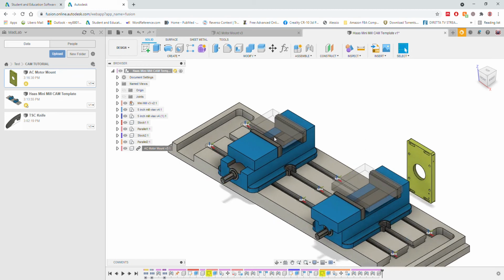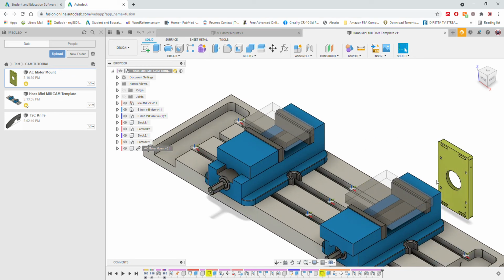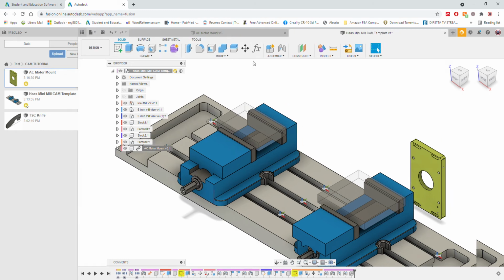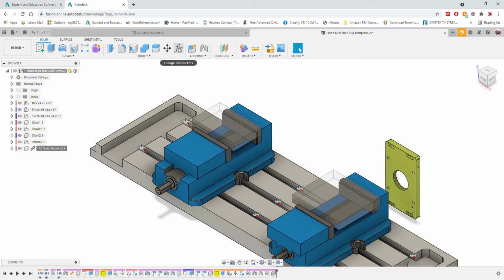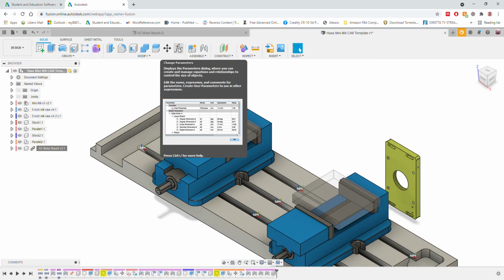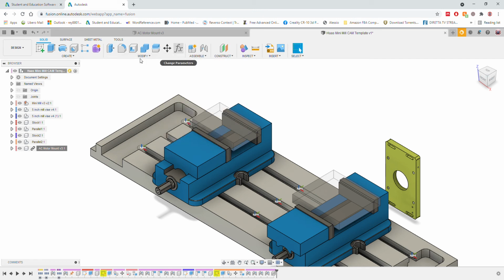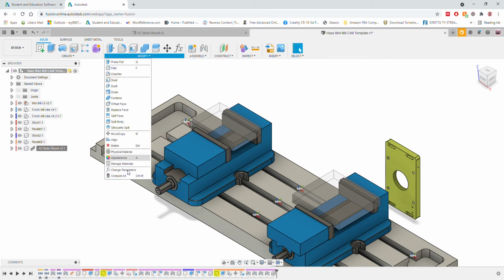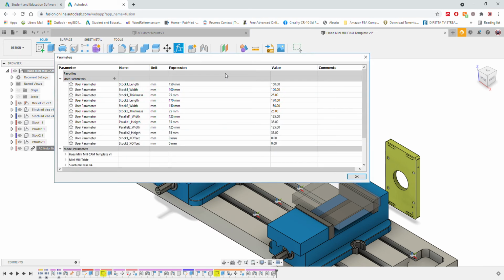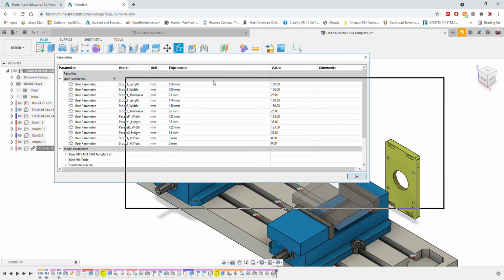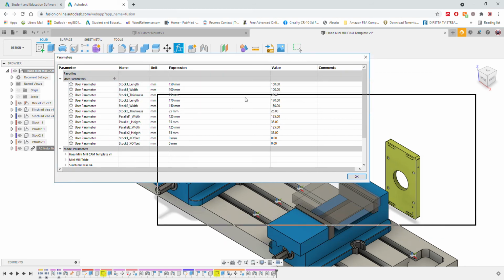So the first thing that you want to do is either join it there, so link it in one of the stock, or prepare the stock before. So we can close this window now. You go in the parametric tab. If you don't have it here, you just have to modify it. It's here at the bottom. You click on the three dots, pin to toolbar, and then you have it here, which is really useful.